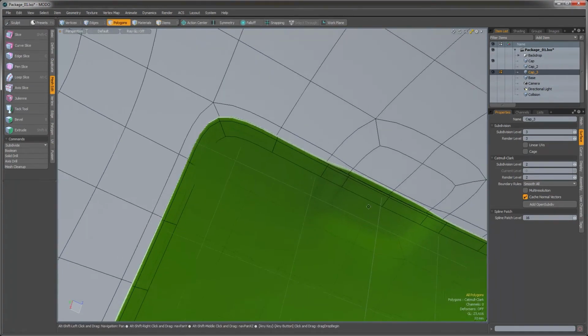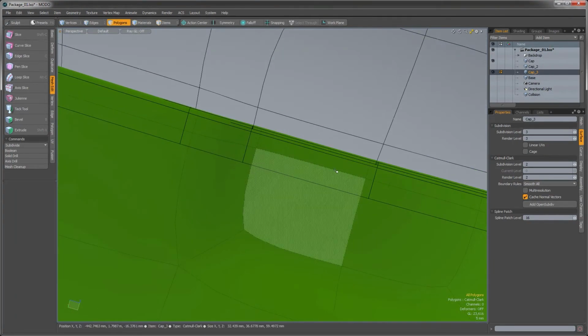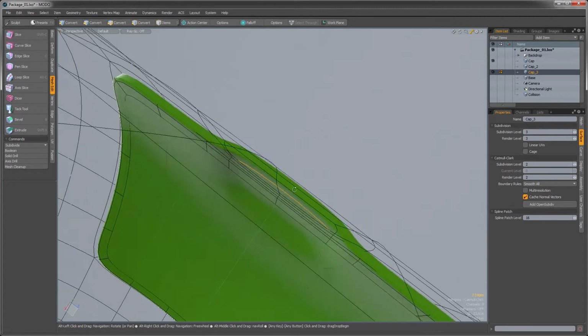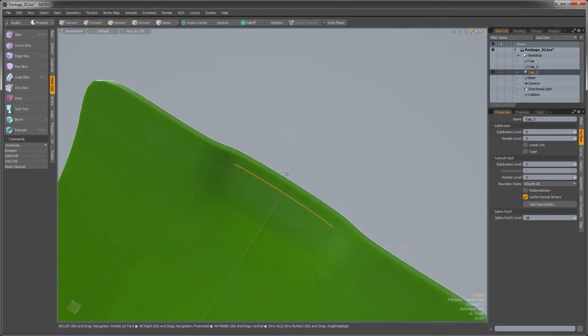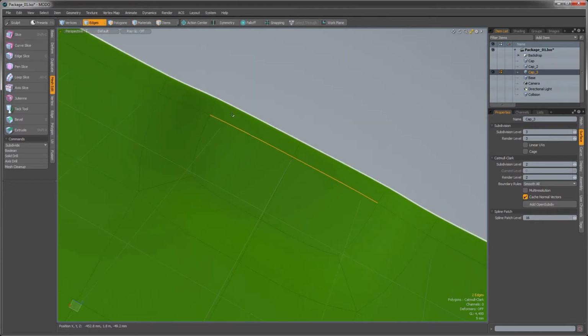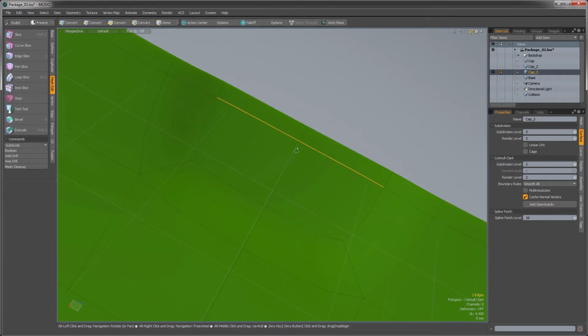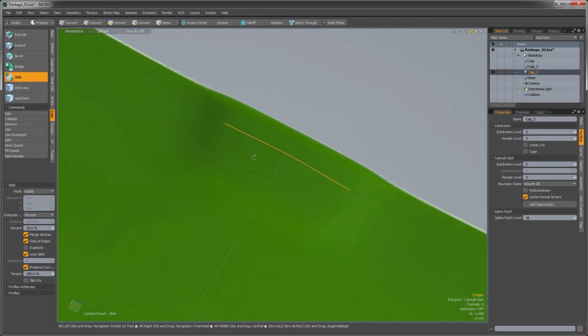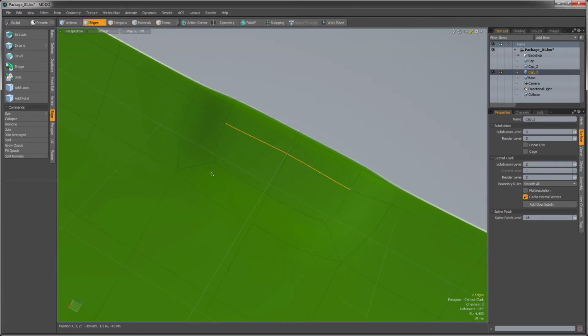So kind of an extra little detail that I want to add inside of here to help seal this element is I'm going to grab this edge underneath the lid. We can turn this off. So if you have your polygon edges visible, there's just this little edge now that's created right inside of here, inside the thumb indentation. So let's go here to edge and slide that back a little bit. Slide it back just a little bit, maybe that much. Q to drop the tool.